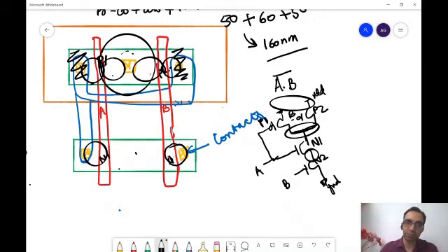Even the capacitance of the field also reduces because we have the shared drains, right? Between the gate and drain, gate and source, there were 3 components, right? So that field also, I think, reduces because of this. Yeah, because the drain area reduces, that can reduce. Yes, that will also reduce. The poly to drain capacitance would also reduce because the drain region is smaller in total length, total area.